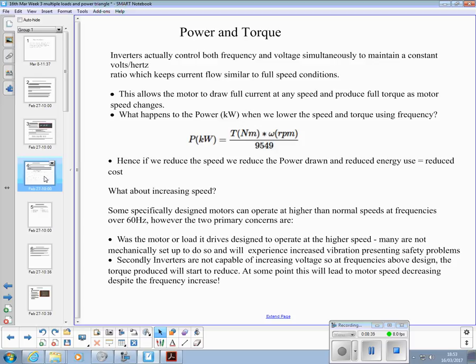Yeah. So if you've got a system where you're running a pump to a tank, and that keeps turning off and on, you may use less energy if it ran at a constant speed, or a controlled speed to feed the tank and keep a level. You might save energy. One way to think of it.